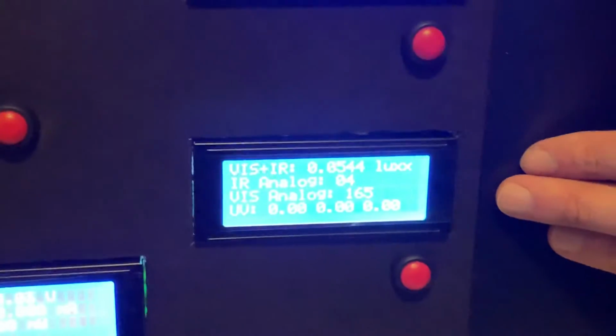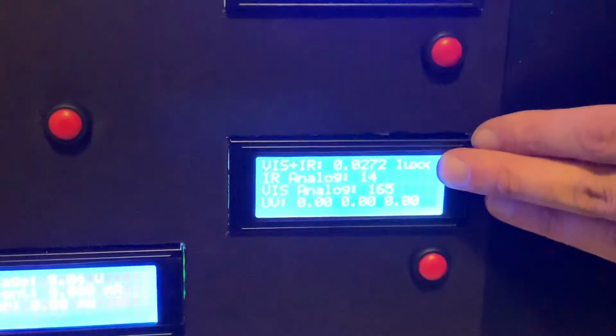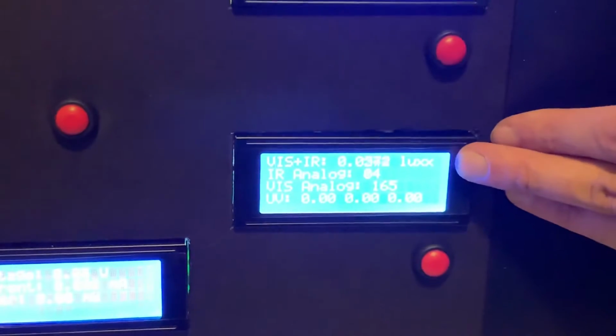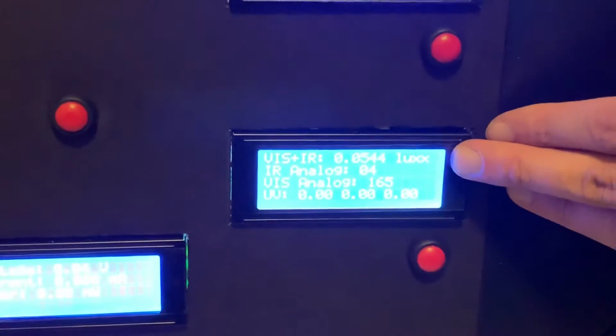One of the last ones down here in this column is my spectrum calibration and response subsystem. You want to know exactly what you're putting into the system, so you can put this in there before you put the airfoil in to make sure you're getting what you're supposed to be getting. So I can get my visible and my IR intensity, my luminous flux intensity in terms of lux, right there.